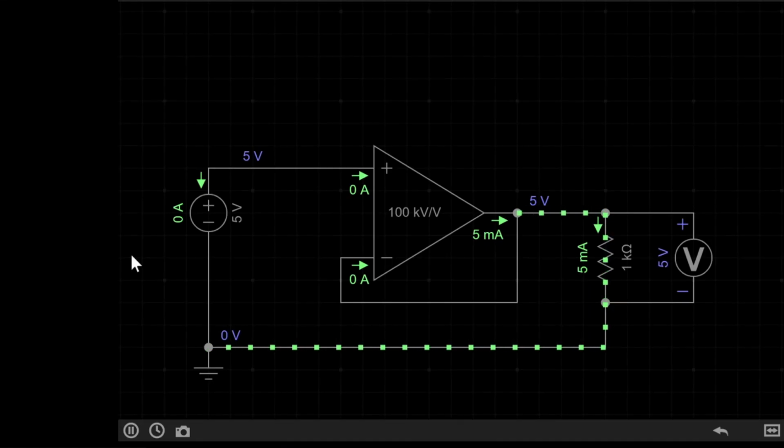Hi. An operational amplifier, or op-amp, is fundamentally a device that amplifies voltage with external feedback on and across its terminals. Basically, placing resistors and other components between its input and output terminals defines what kind of amplifier it is. This circuit I have here is a simple voltage follower. Before we discuss the circuit, there are a few things about amplifiers in general I must mention.